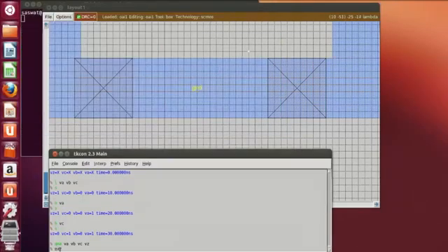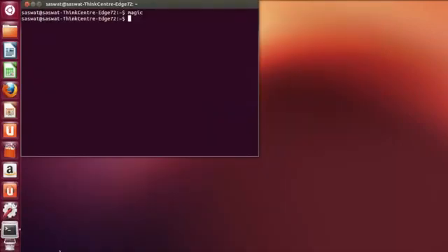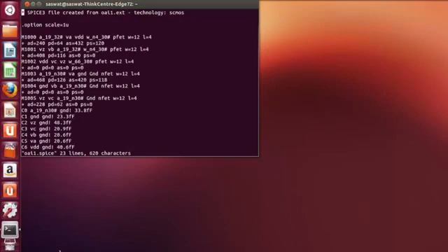Then exit. You want to see the spice file, then type vi OAI1.spice. This is MOSFET 1, DP FET W/L is 12/4, all are 12/4. Similarly, you have the area of diffusion, the same thing as we have seen earlier.